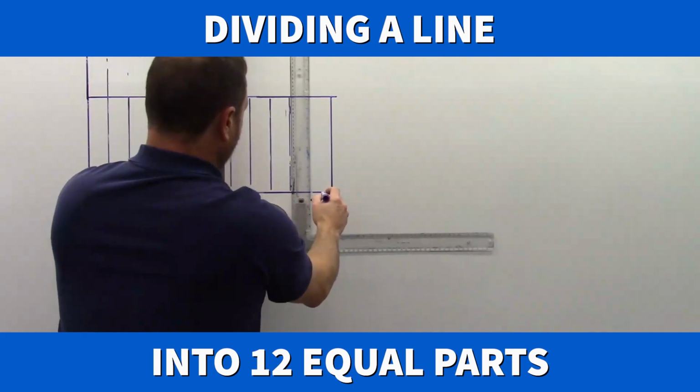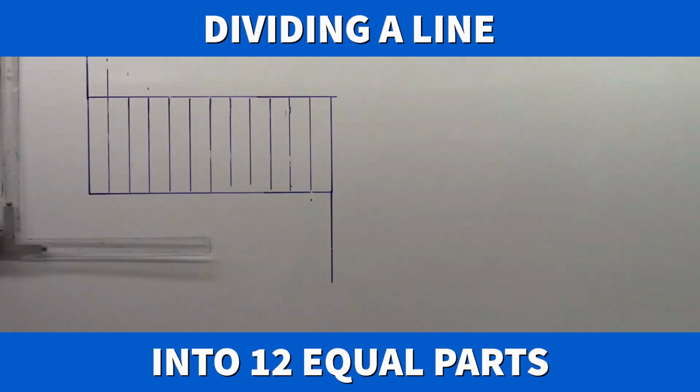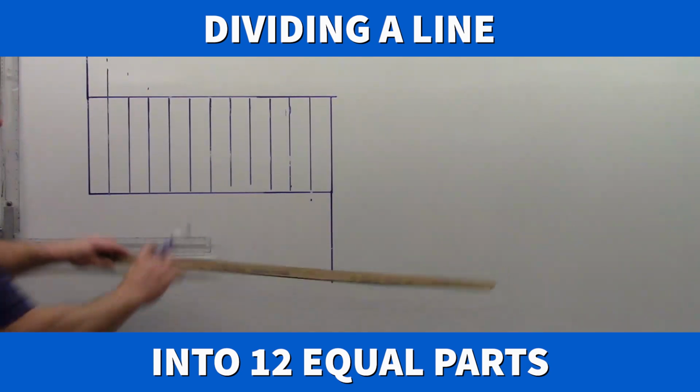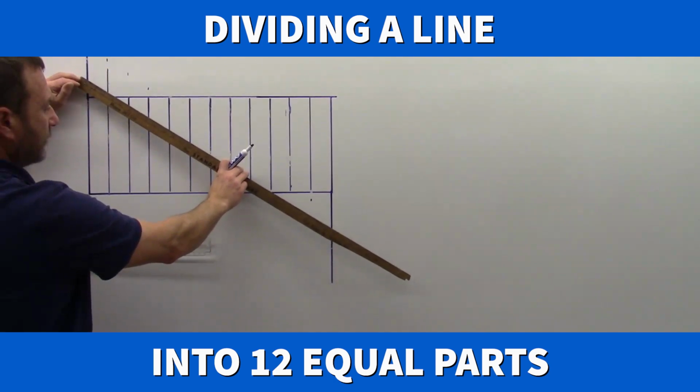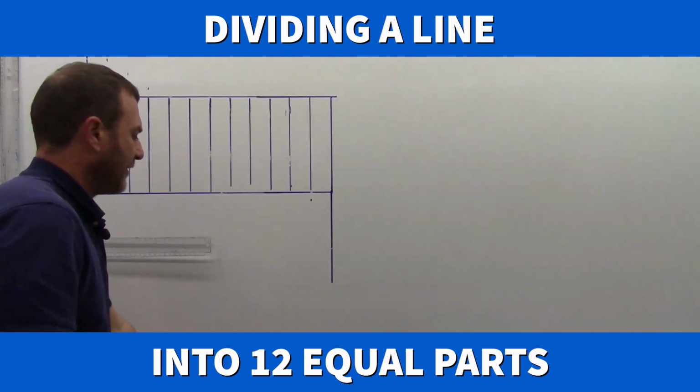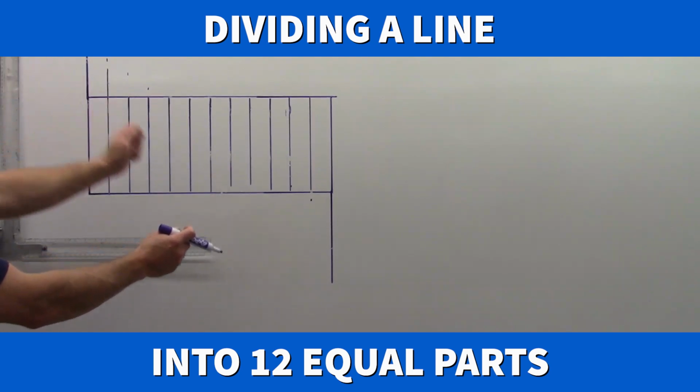And again, it doesn't need to be 12 divisions, so we could do this in 6 or 9 or any number that we required. The component is finding that, getting your ruler on an angle where the number is easily divisible by the number of spaces that you want. Okay, so that's the key to this one. If you want it in half, then go to a whole number that's easily divisible in half. Or if it's thirds, pick one that's 9, 15, 18, things like that. So you find the number and then you divide that through to find out how much on the ruler you're going to tick off.